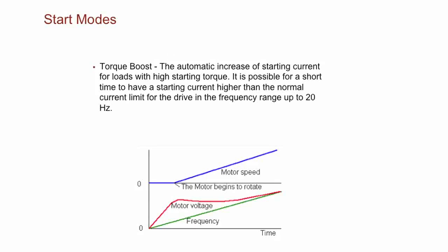Normally this is the volts per hertz curve. It goes up on this curve where your voltage and your motor speed are 1 and 1. You can also increase the motor voltage higher at low frequencies to give more torque to break away, and then bring it back into the normal ramp. So if you have a load you can't get started, a lot of times we'll say go crank up your V-boost a little bit and see if we can get it to start.